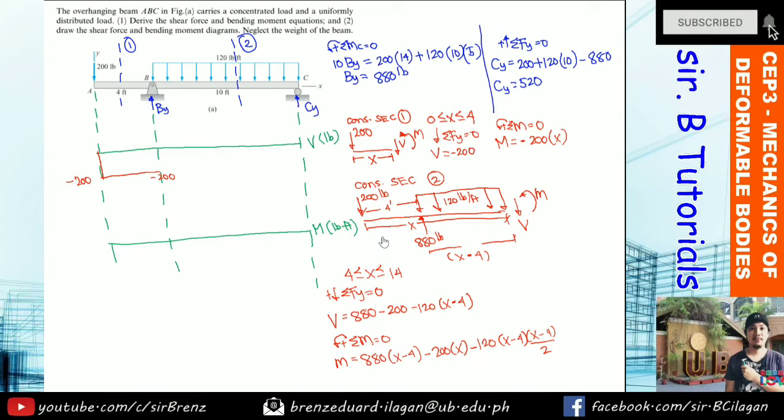Okay, next. So this time we will now use this equation, okay? And as you can see here, may concentrated load, yung reaction mo pataas. So magkaaroon ka ng dalawang value for the shear at point 4 meters away from A, o dito sa point B na to. So ang gawin mo, input mo lang sa calculator ulit ito. So 880 minus 200 minus 120 times the quantity of x minus 4.